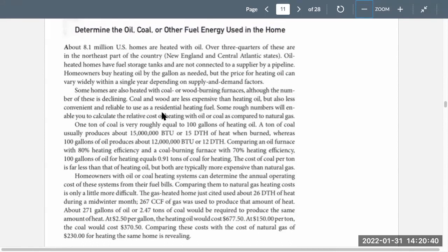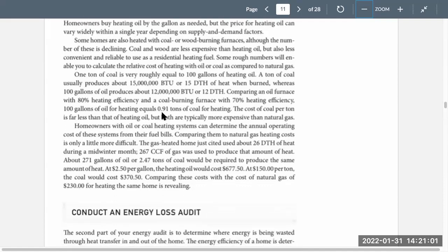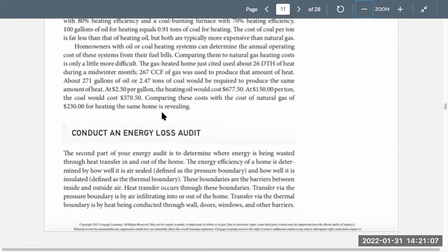And you could do a full energy audit and try to determine where their BTU losses are, and you could determine if their furnace is too small when it comes to replacing the BTUs they lose through their walls, their ceilings, and their floors. Again, electric bills go a long way. We can find out a lot of information by just looking at someone's electric bill.